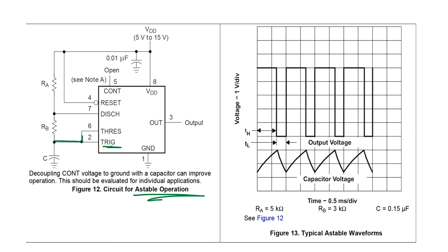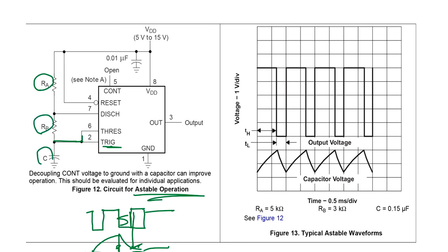That means when the trigger goes low, then this drops by discharge, then this triggers again. Having this trailing edge, the trigger will be here. Okay, so having RA, RB, and C, we connect the trigger input from this output, so we continuously trigger.